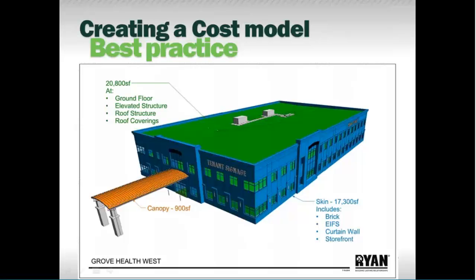But those system parameters, so in this case the skin is 17,000 square feet, and it includes this mix of materials. You can kind of understand, you could put a dollar per square foot for this system just based on that number, or you could even break this down to some percentages. And what you would be thinking about is we have so much brick, well, it has a backup wall that needs to be included. EIFS, it has a backup wall that needs to be included, curtain wall and storefront. You could break those out individually, or you could say, hey, this is going to be a $35 skin, all in over 17,000 square feet.